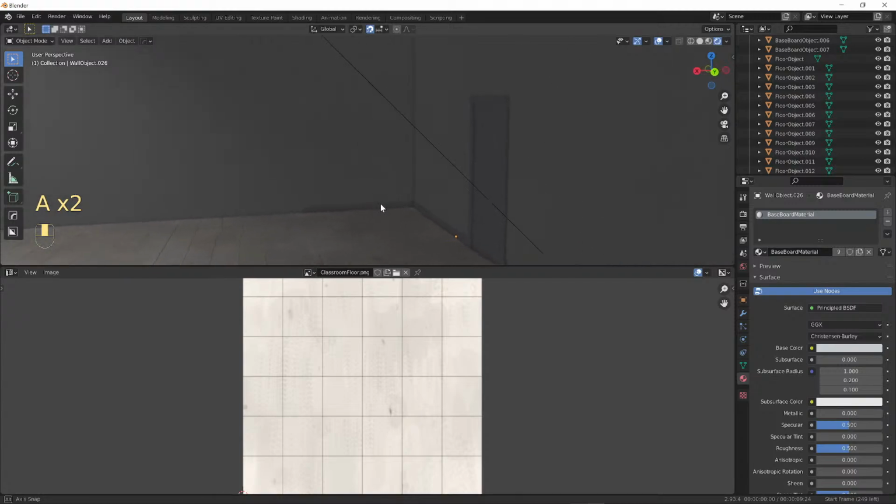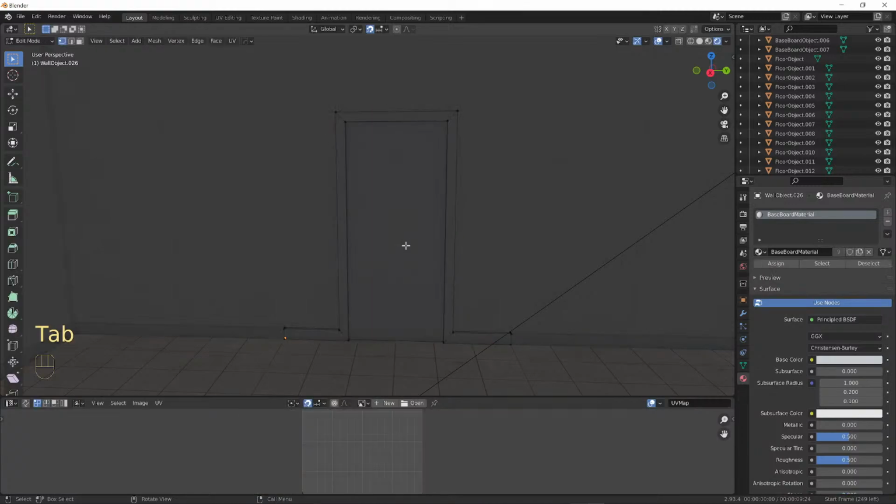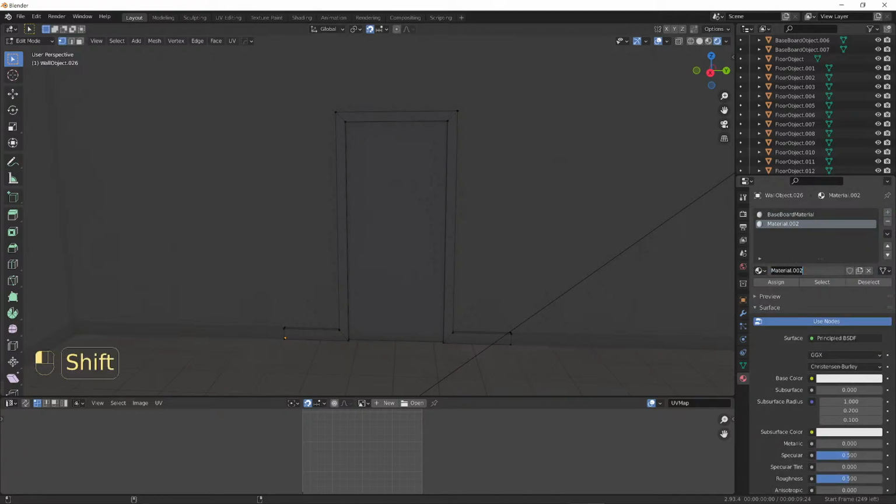All right, so we've talked about this before, but let's cover it again because I recognize we covered it early on. We want to have two different textures applied to this, two different types of materials. One for the door and one for maybe the trim or the frame here. So we'll go in here, and where we have the baseboard material applied to everything, we'll just hit the plus here in our materials tab. And I'll go for new, and we'll call this door material.